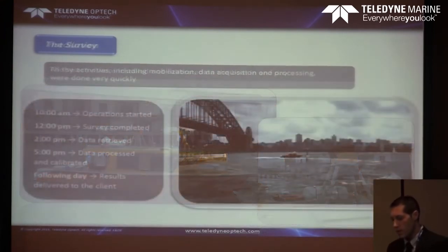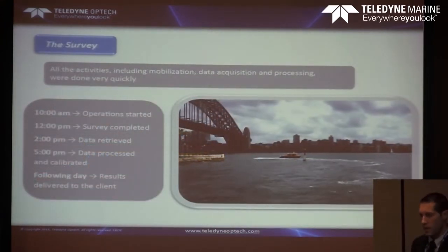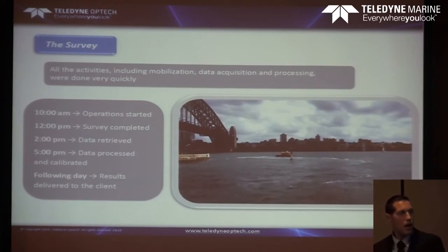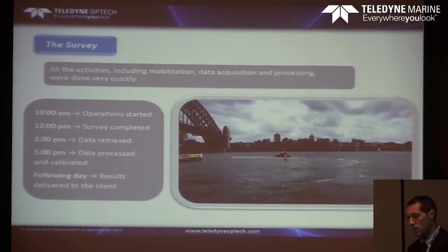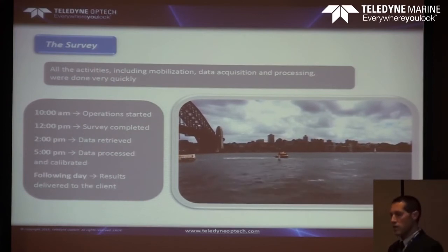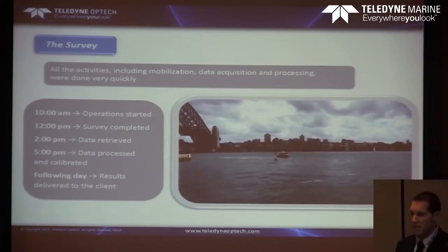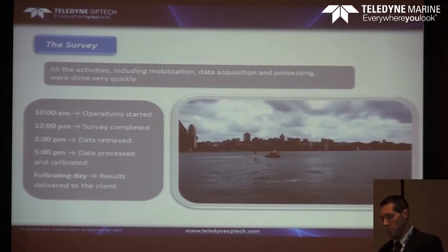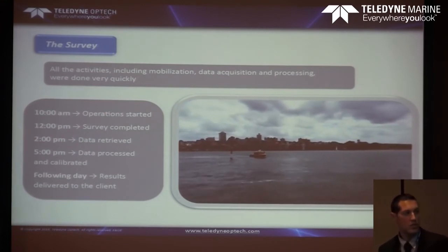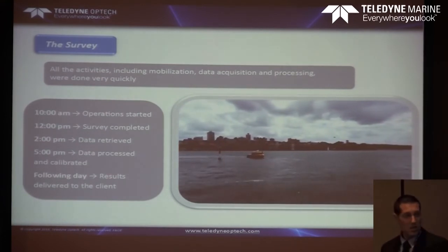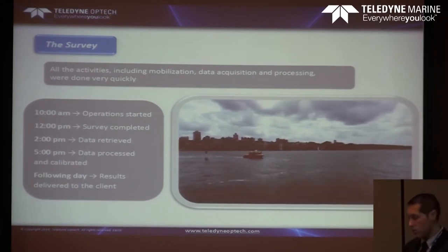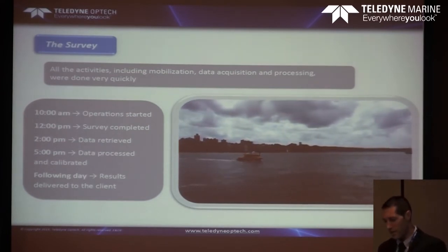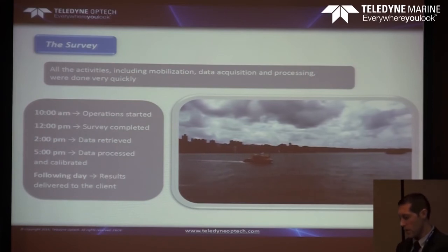In this case, we did everything in one day, which is very impressive. We started at 10 a.m. with the mobilization of the equipment. We did all the installation, which takes half an hour. Then we went out and did a bore sighting. We started the survey at 12 o'clock, at noon, and it took around 2 hours. We did multiple passes, and we also tilted the multibeam as well.